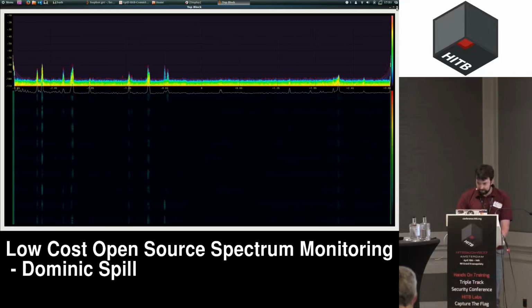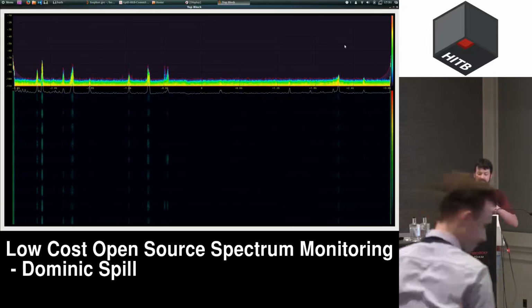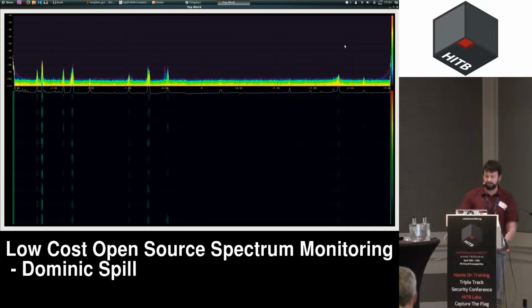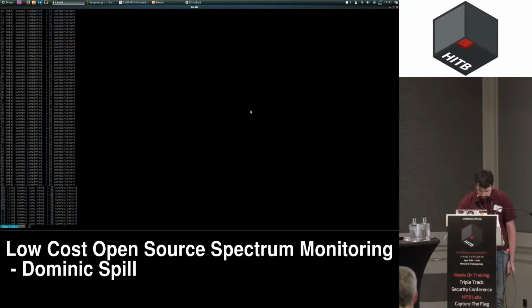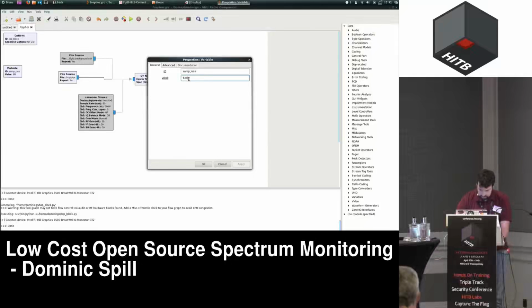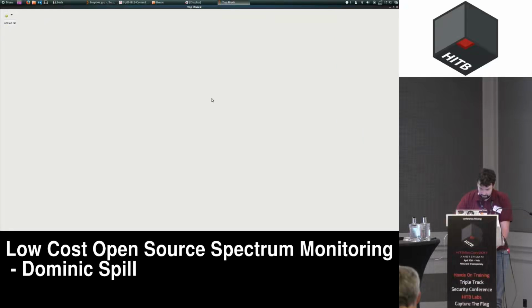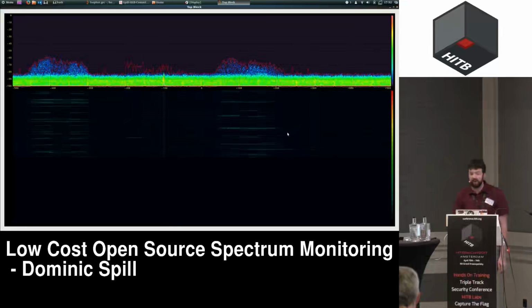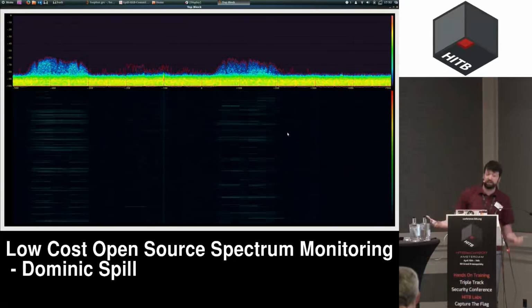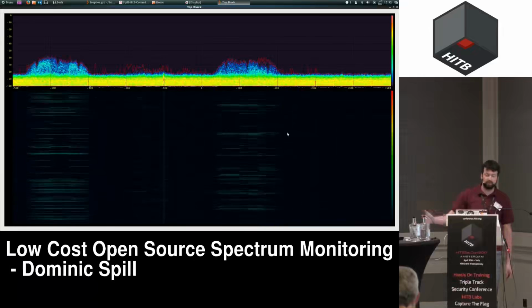And so we're able to view the data that we had captured as disparate wide sweeps in almost real time in tools we know, and we're able to identify transient signals this way. So if I run the same thing again, but I limit my frequency range, my sample rate is 100 megahertz wide now. This is the 2.4 gigahertz band, and it's sweeping the whole thing significantly quicker, because it only has to do 5 hops to get the whole thing at 20 megahertz a chunk.